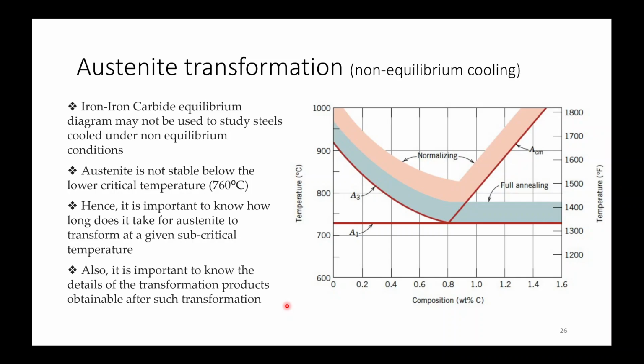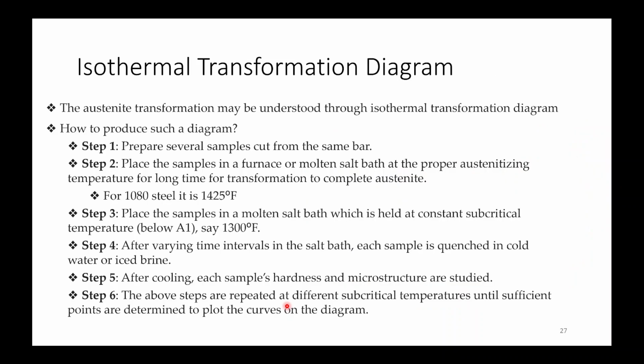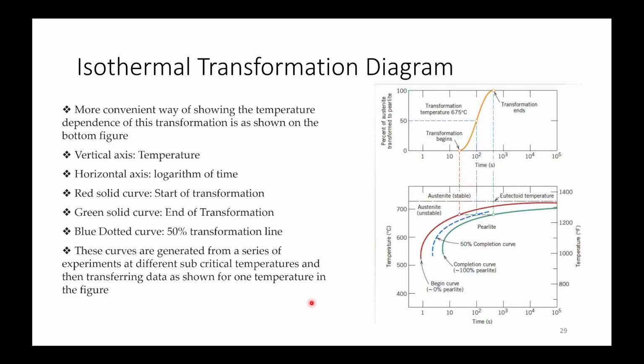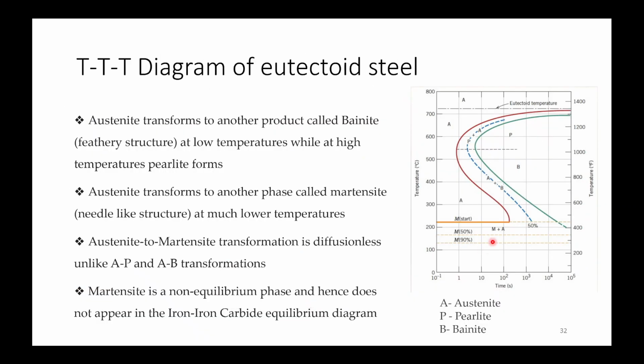Change in structure depends on temperature. If we suddenly stop cooling in between Ms and Mf, say you're cooling only up to 50% martensite and you just stop, with time it won't change the percent fraction of martensite. Then the remaining austenite will be retained austenite.